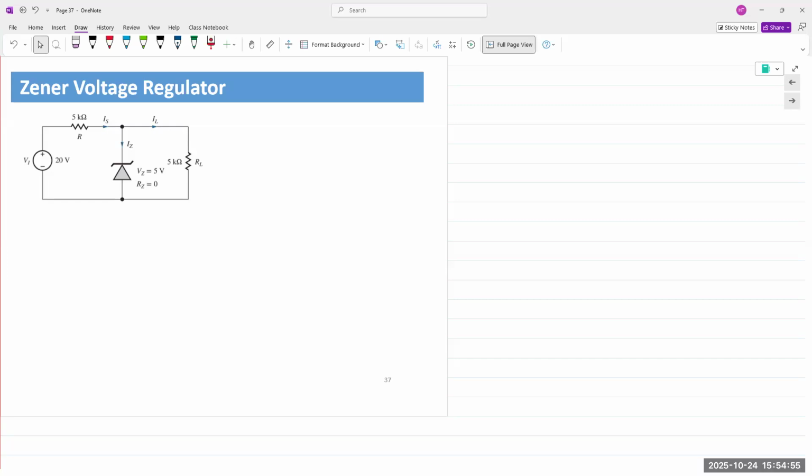Now, the reason why this happens is because it is a very heavily doped junction. So right from the beginning, it is designed to break down very quickly. Very quickly in the sense that if we design it to break down at 5 volts, it's breaking down at 5, 6, 10, 15, 20, 200 volts, whatever the design could be, right?